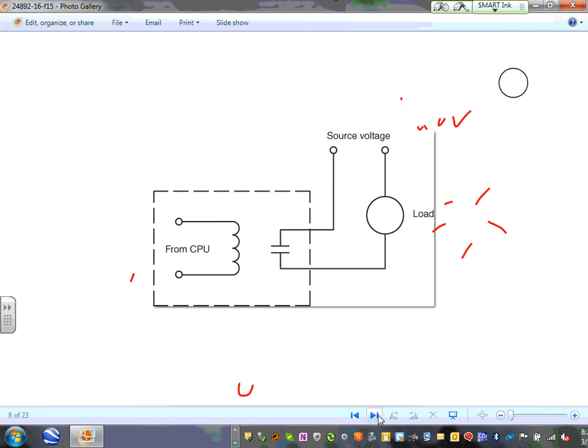A relay is very similar to the relays that we have. So you get the 24 volt here, 24 volt. You energize this coil. This will close and does the same thing. So either transistor, triac, or relay. Triac or transistors are typically the common ones to get you an output.